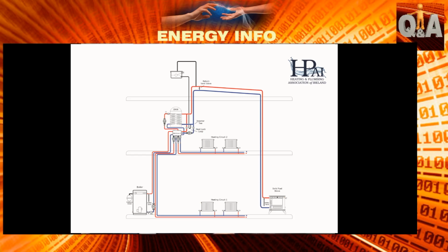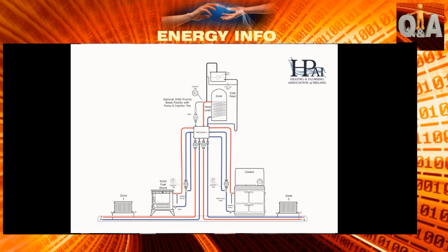You can actually put faster water through the coil if you want and heat the cylinder quickly, and yet you're not interfering with the open circuit of the coil. But the main benefit is you've only got an indirect cylinder and yet you've got two appliances. I was just going to say that, Harry. There's only one coil on the cylinder, yet there's two appliances. Well, what's very important is the size of the coil, because if you have a standard 3 kilowatt coil, there's no point putting that onto two appliances.